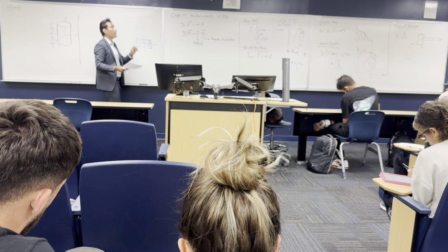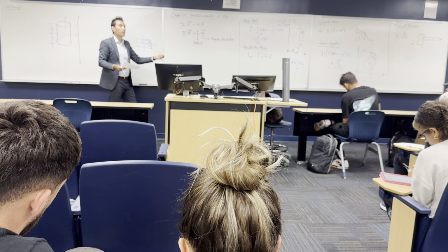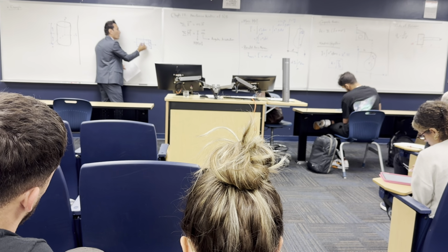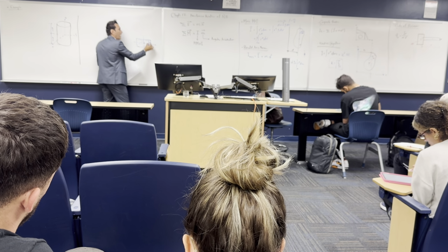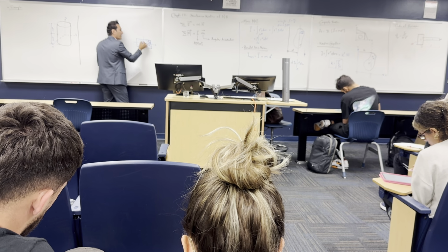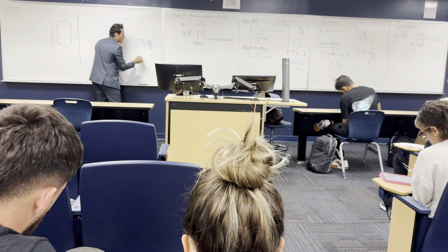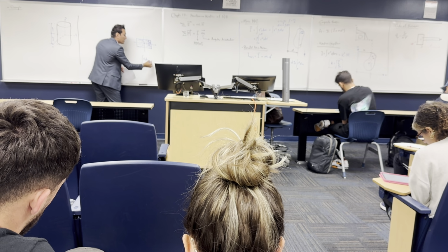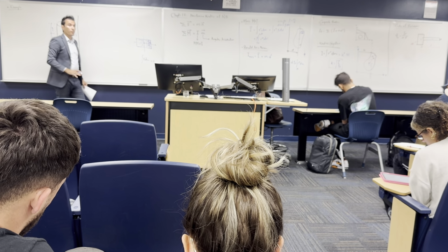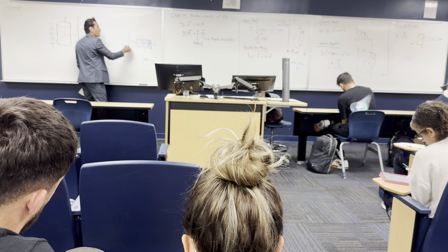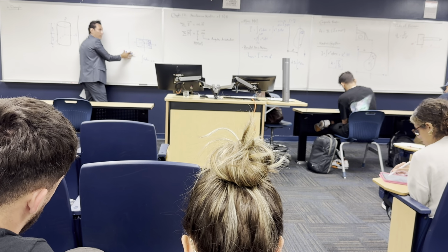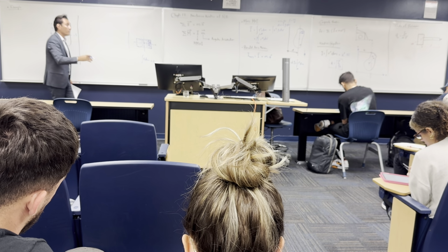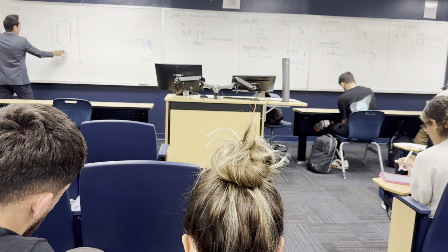But if we are getting the first moment of a mass, the first moment of a mass about the CG is always 0. Why? Because you will have this mass crossing this mass and this mass crossing this mass. So it's called r dm. About the CG it is always equal to 0. But you can get r dm about another axis. Right? That's what I want to say. Same thing with this, the first moment of area is always 0 about the CG. Anyway, let's get back here.